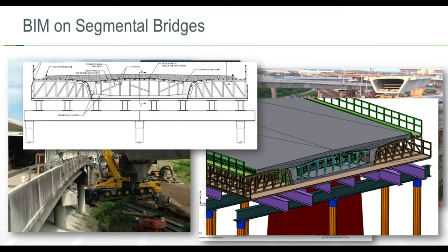On a segmental bridge, we use them a lot, as you see here. Having an accurate geometry of the new bridges, existing bridges, if we're planning in this case, as you see here, some demo and erection, being able to verify that yes, our plan will work, we can fit the cranes in where we need to. We'll use those same models, say for in the case here, for false work designs, so that we can rapidly get out accurate geometry, accurate weights, dimensions to verify as a sort of a second check that our false work design is adequate, that we have the proper elevations, we have everything that we need to go ahead and build the work.